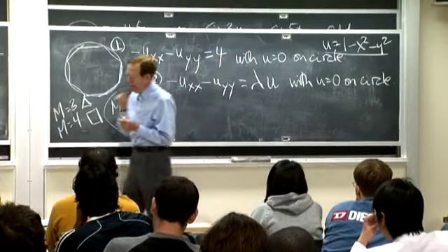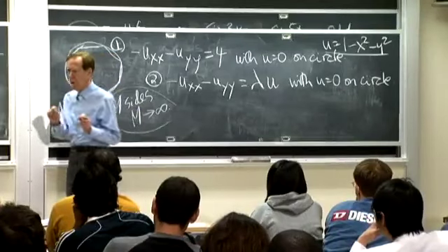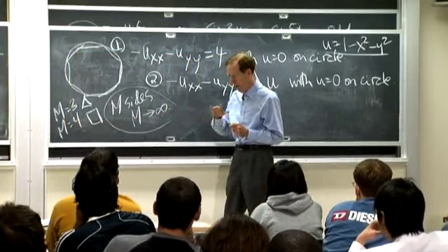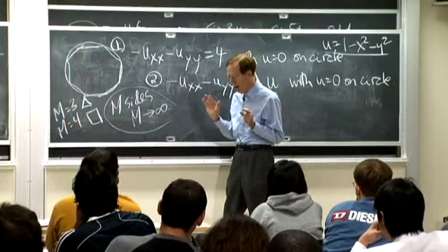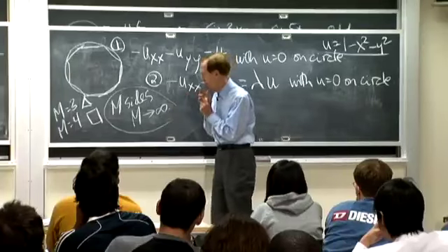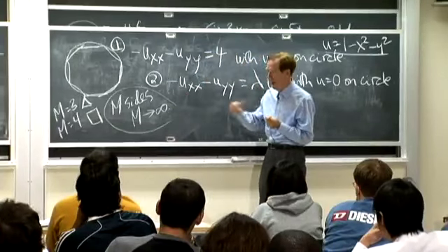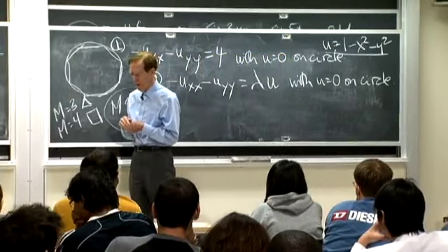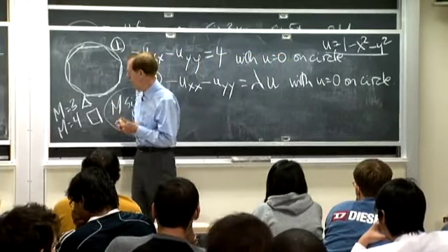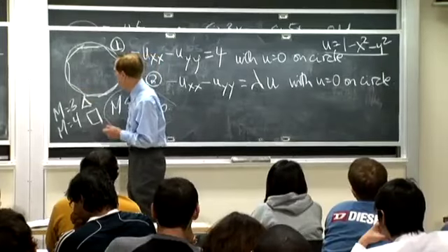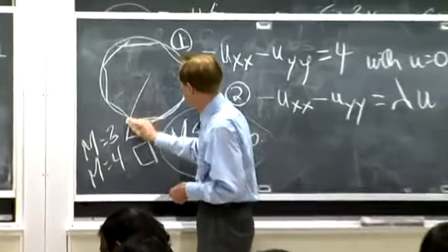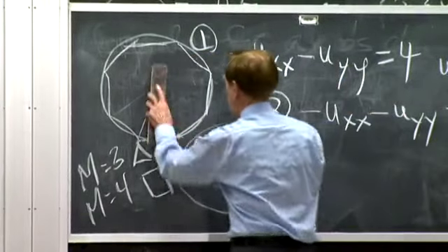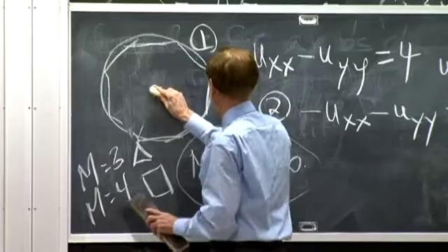There is one thing: the code we're working with uses linear elements, right? We're using linear finite elements, so we're not getting high accuracy. So I would really like to move up to quadratic elements. Let me draw the one that we've drawn in class before.